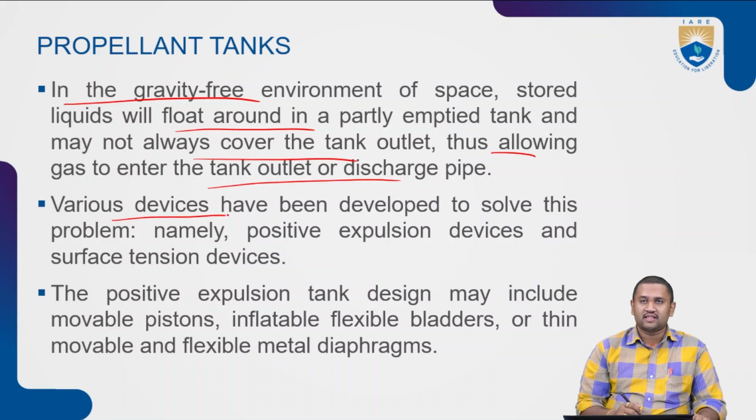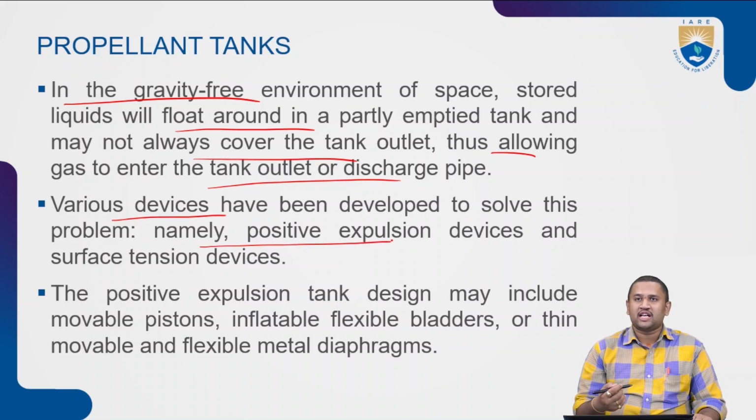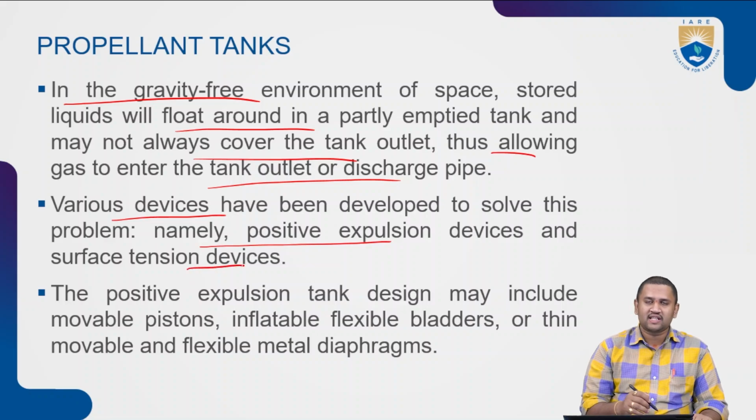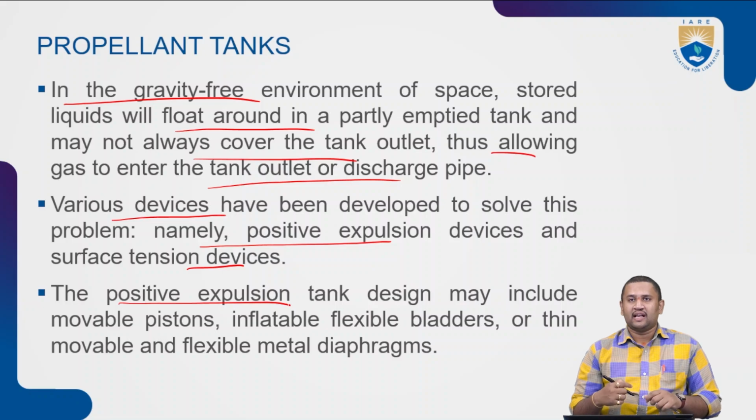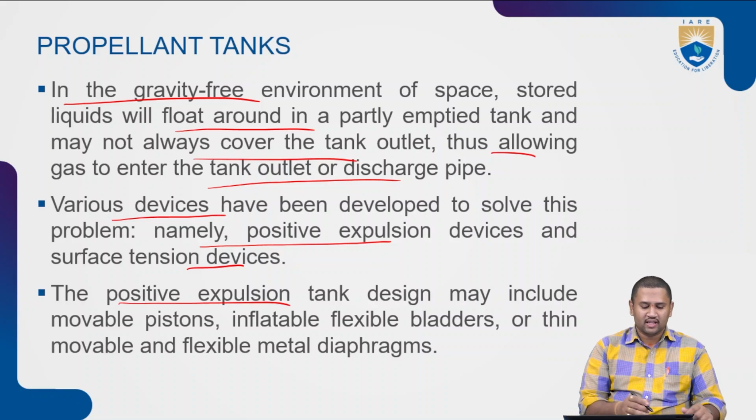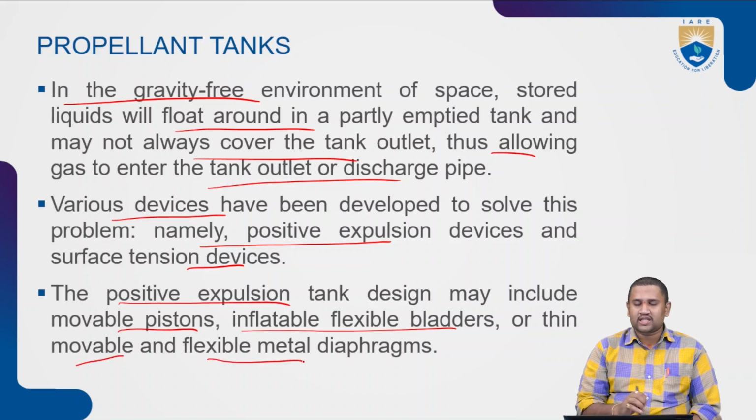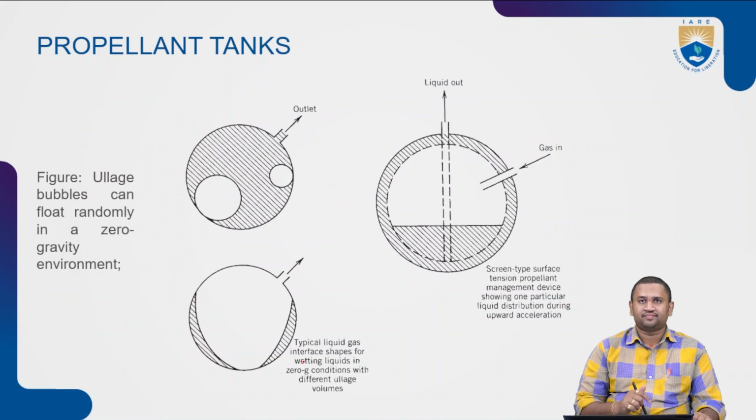So various devices have been developed to solve this same problem, that is, positive expulsion devices and surface tension devices. A positive expulsion device is a simple design with a movable piston, inflatable flexible bladders, or thin movable or flexible metal diaphragms.